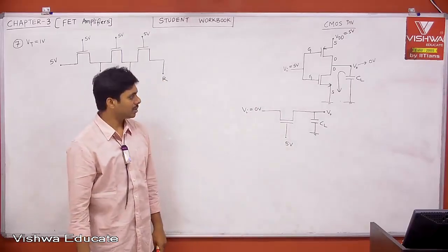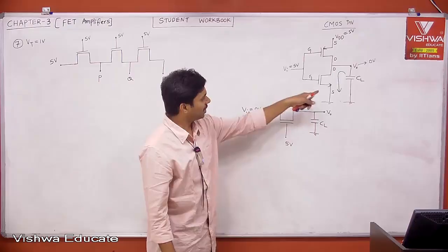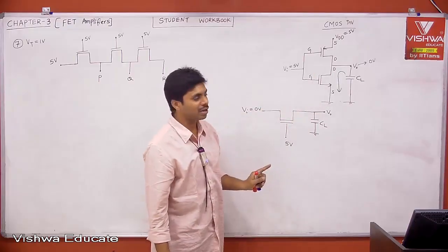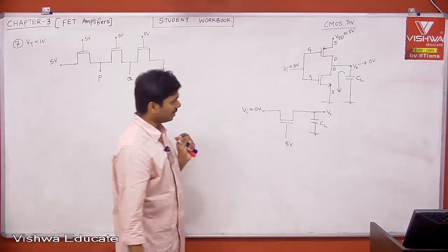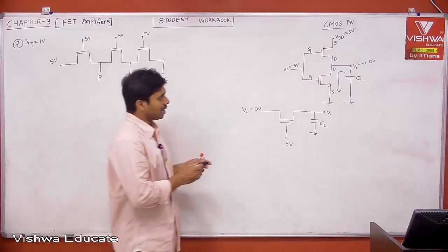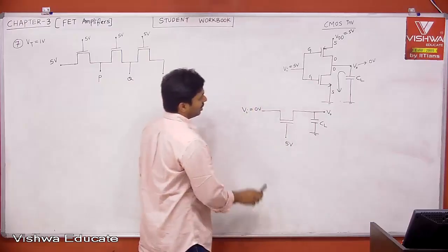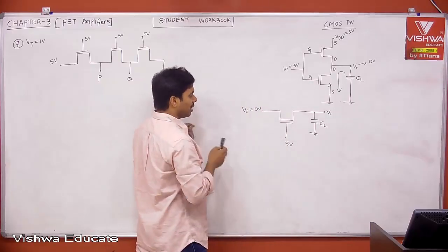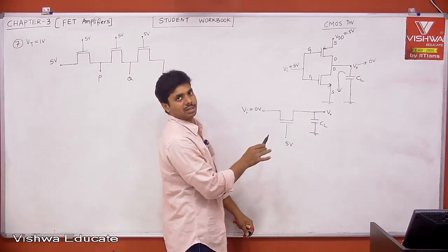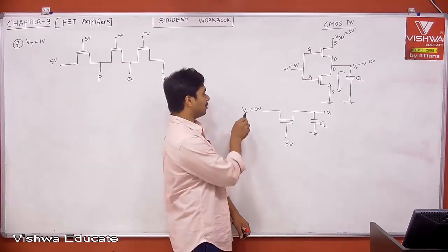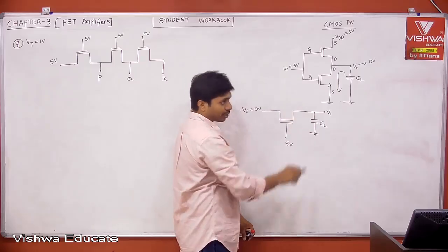Now imagine, I didn't say which is source and which is drain. But here you clearly know which is source and which is drain, because the source is always the lower potential. Now tell me, let us say this voltage is greater than or equal to 0, then definitely this is the lower voltage, no doubt about it. The terminal that has the lower voltage is the source. For example, if this is 5 and that is 5, then this will be the source.